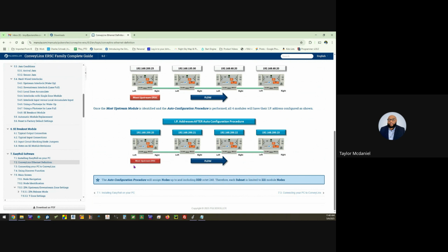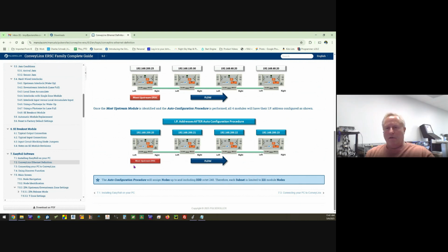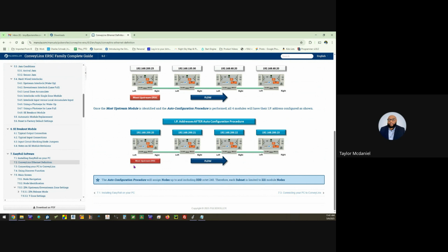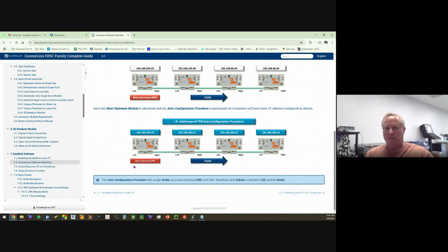I was thinking, how many cards, every 12 cards stagger them? Stagger every 12. You could have 10 cards at 10 milliseconds, 10 cards at 11 or 12, 10 cards at 13, things like that. Just a slight little difference keeps every card from being hit at the same time.